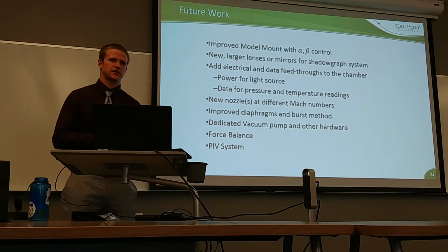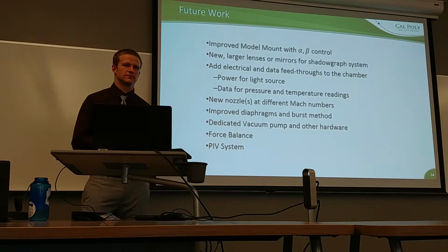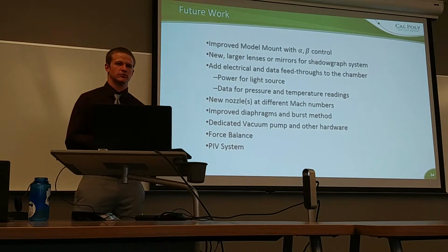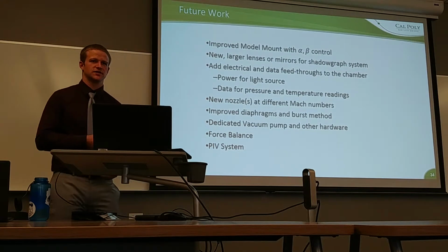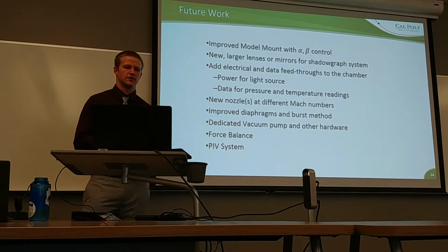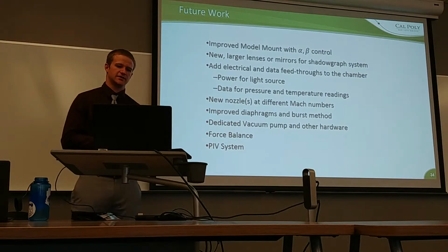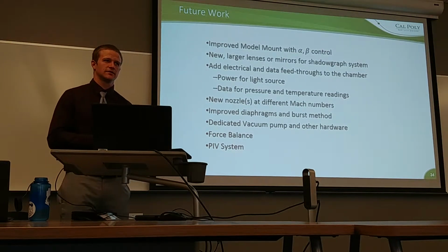That is possible. I think it's about Mach 1.4 if I'm correct for air. I believe that under 1.4 you can't really get oblique shock waves, as you just have a detached bow shock. So that's possible. Yeah, that's possible. I did not look into that, but yeah.